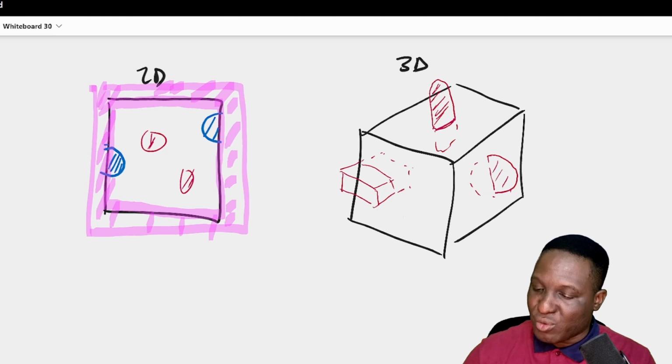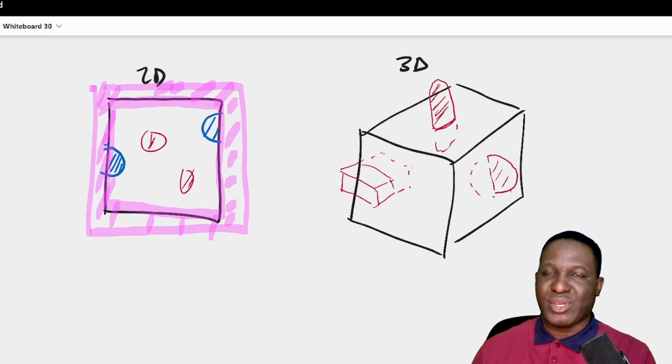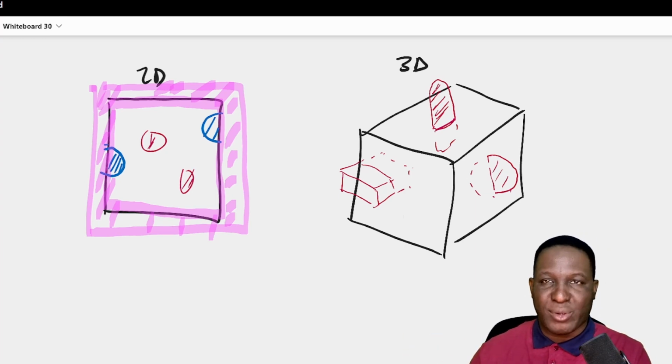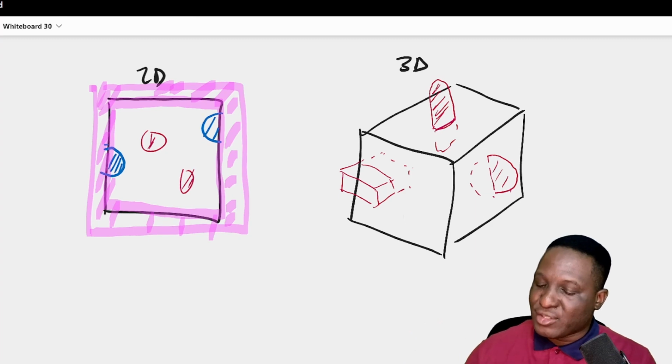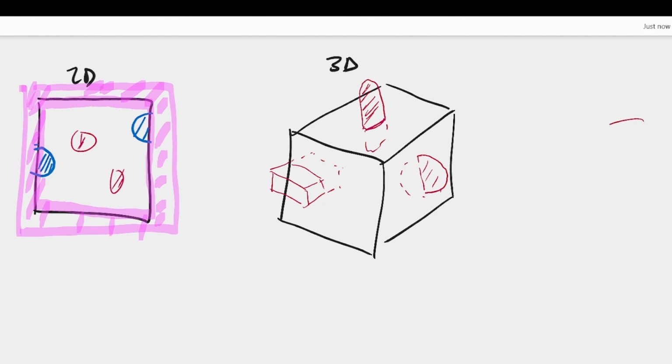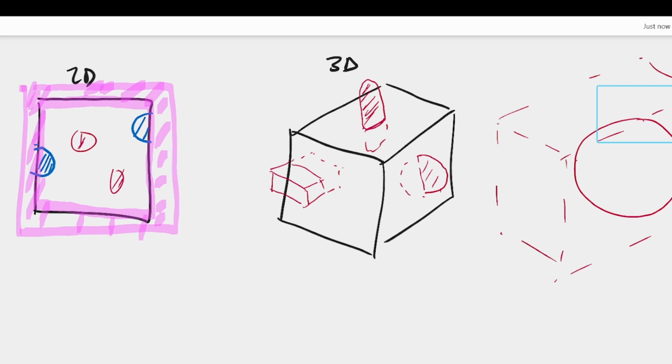So clearly what we need to do with the 3D cases is a similar situation where we isolate the particle that we want, and then we extrude cut it. So let's say in this instance, I'm interested in a spherical particle like that. I need to locate where it is in space. If I can find out where it is in space, maybe somewhere around here, that's where we will need to extrude cut the system.